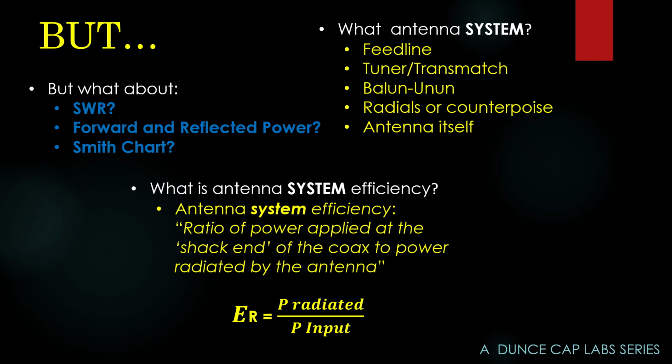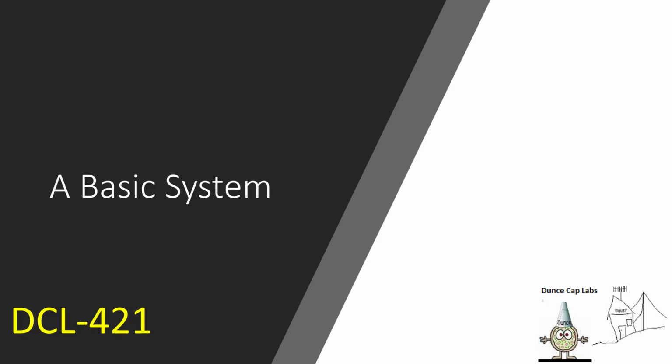The efficiency of the antenna we can't change, we can't even measure. We can assume it's pretty high, and it usually is. But what we really can have power over is how well the antenna absorbs the power, or how well we transfer power to the antenna. That is the most important thing going on here.